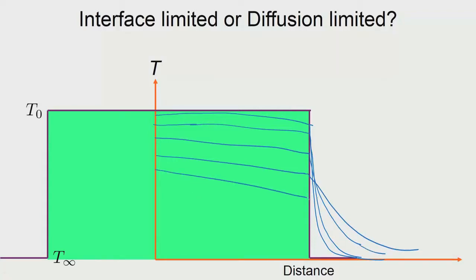and if this is the situation, what it implies is that the surface temperature is dropping roughly at the same way as the interior temperature is dropping, and the gradient inside the bulk is very small. Okay. And this is a situation where the material is made up of metal, which is a good conductor, and we can now see that the rate at which the heat is lost from the body is limited by how the temperature is dropping at the interface and how the heat is actually taken away at the interface. So, this becomes a limiting factor. So, which means that this kind of heat transfer is called the interface limited heat transfer.